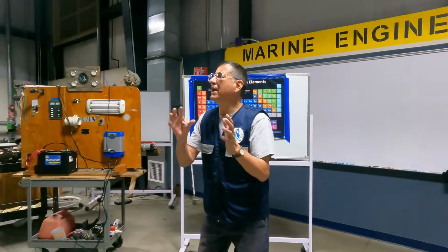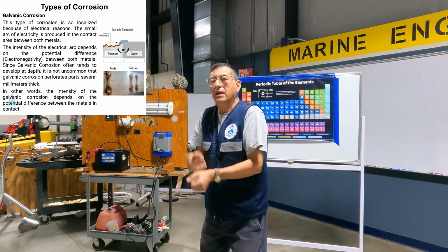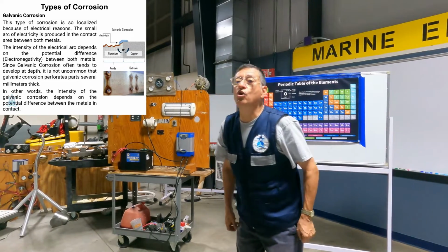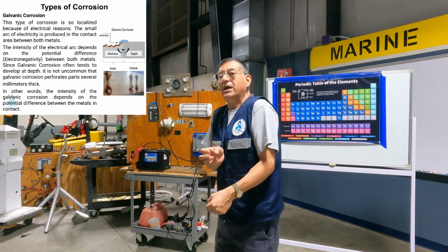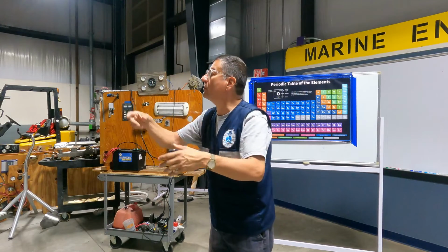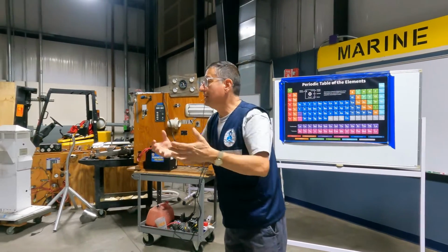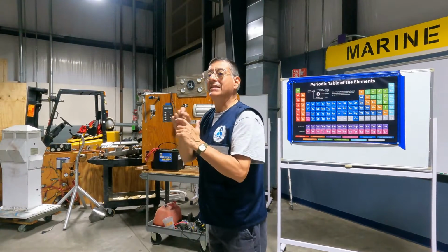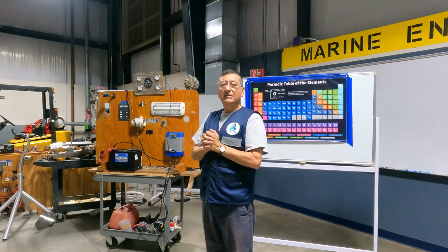What is the name of that corrosion when you have 2 dissimilar metals together in a marine environment and the element with more energy attacks the element with less energy? Galvanic corrosion. And what happens if you have that situation, 2 dissimilar metals together, and additionally, for some reason, internally in that refrigerator, 1 cable with power is touching the housing? You have electrolysis, because you have galvanic corrosion plus current, and the current accelerates that process. This is part of the course of corrosion, but this is later.